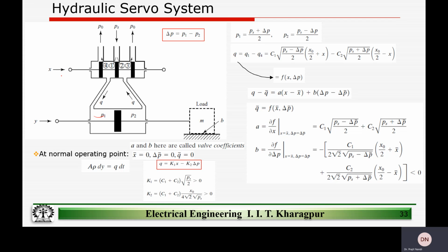I mean, we pushed this guy here, because of which we established a pressure differential across P1 and P2, and because of which a fluid started flowing. The fluid started flowing in this direction, establishing a pressure differential on this, which is going to be responsible for movement of mass m, right? So we equate the volume of the liquid that has circulated because of the movement in x.